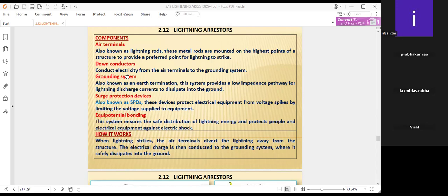You have to select the materials so that the electricity reaches the earth cleanly, without damage to the building, humans, animals, or objects. We cannot control the source, but we can control the path by putting robust lightning arresters, and selecting the terminals and electrical conductors very properly before installation.